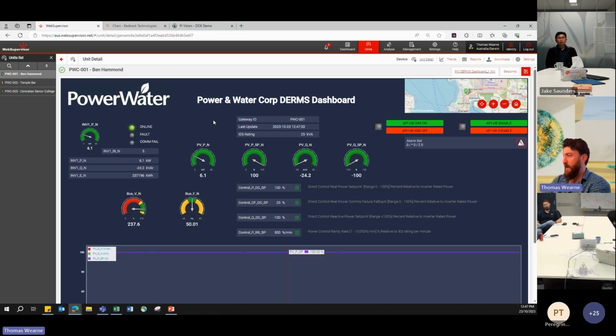Yep. So the active power goes down in this case to 0, and the inverter's going to operate in full Q. And the cool thing about this is, again, that it's not limited by what's happening on the DC side in order to do that. But it looks like it might be choosing to embarrass me, or at least it's holding on there. But you can see that it is working.